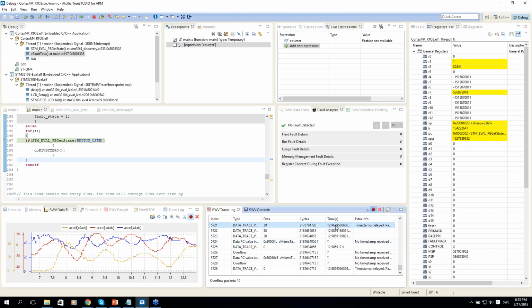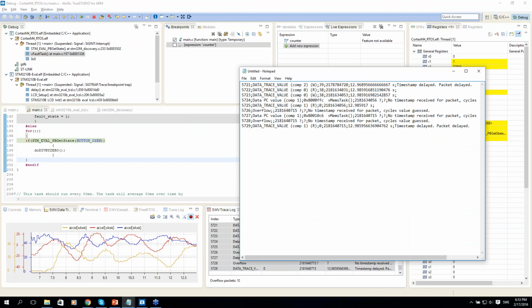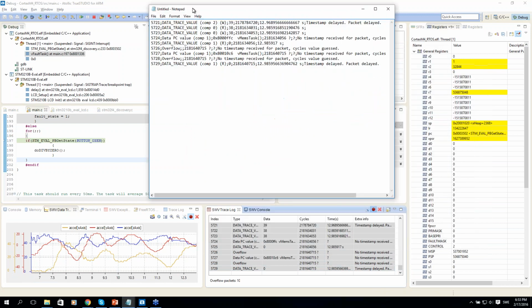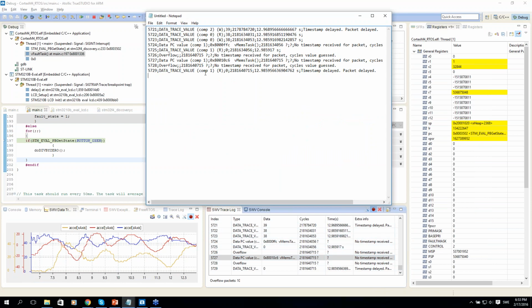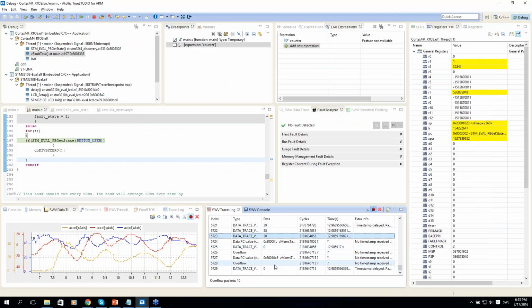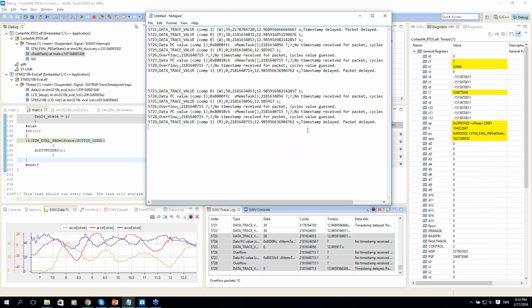What you can do is, the format of the serial wire viewer trace log is a comma-separated value list. So you could potentially export it, or just copy-paste into Excel and do offline analysis if you want to automate this. But I think the question is really about being able to do this quickly on the fly when you're in a debug session.